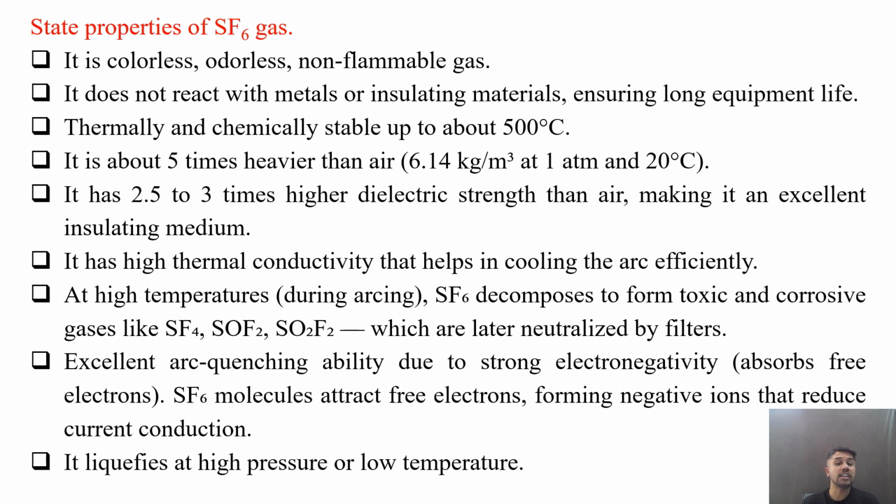Excellent arc quenching ability due to strong electronegativity, means absorbing the free electrons. SF6 molecules attract free electrons, forming negative ions that reduce current conduction. It liquefies at high pressure or low temperature. So these are several properties of SF6.